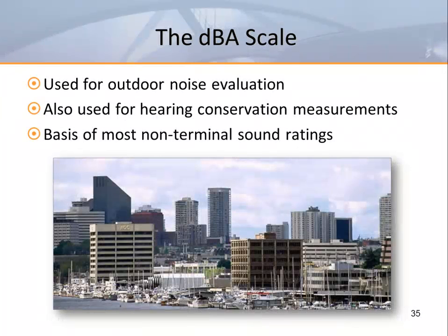Occasionally, customers ask why manufacturers don't include A-scale, A-weighted, or dBA sound in their catalogs. There's nothing wrong with dBA sound, but it provides less information to the engineer than octave band sound power levels. A-weighted sound averages all of the octave bands together to produce a single number rating. dBA sound meters are inexpensive and readily available.